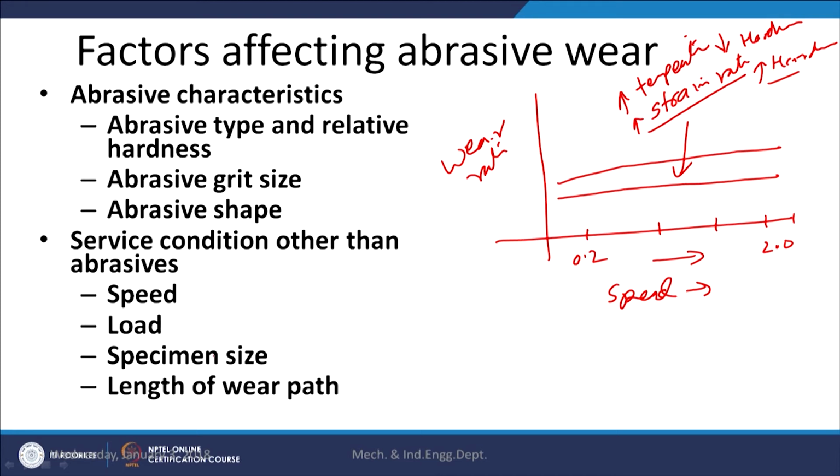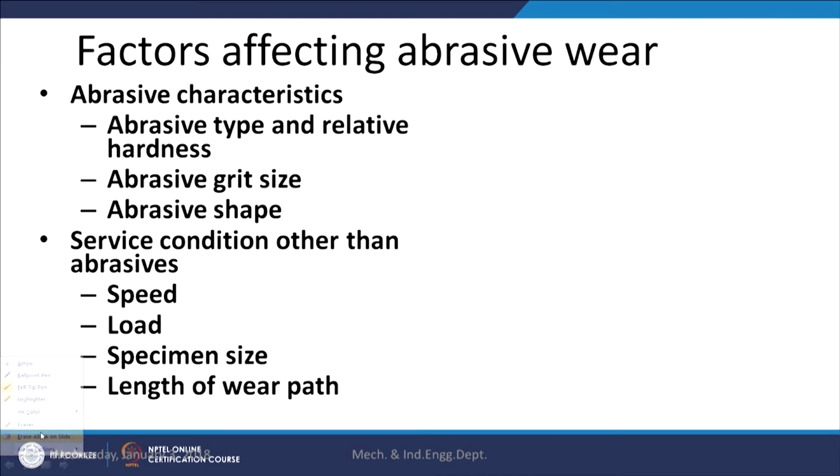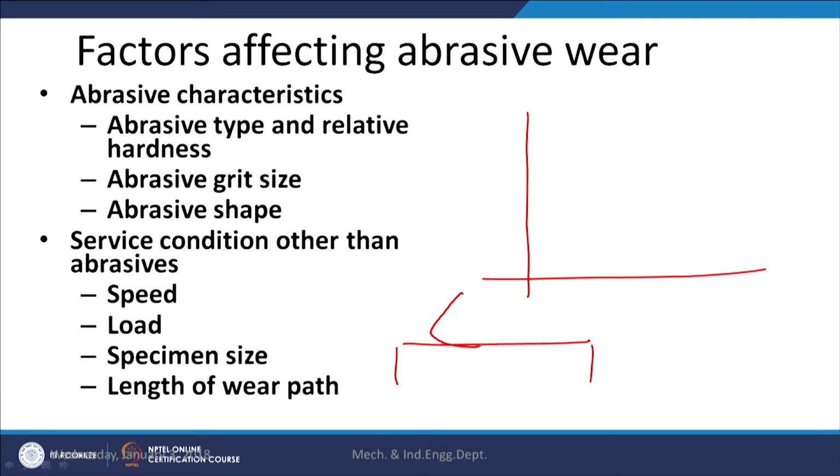Another important factor is the load. Now we know that this is the surface of the workpiece and abrasive load is applied through the abrasive onto the surface of the workpiece. Under these conditions, under identical conditions, if the abrasive retains its size and shape, then an increase in load will increase the depth of indentation.